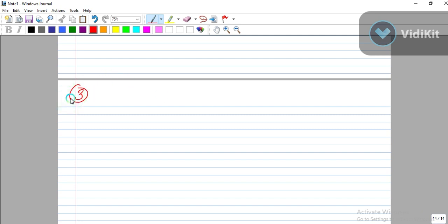Now the third point, what we will see. As you know, I'm writing the current equation on top. ID equal to, I'm keeping mu and COX W by L as K, and inside it was VGS minus VTH, then VDS minus VDS squared divided by 2.